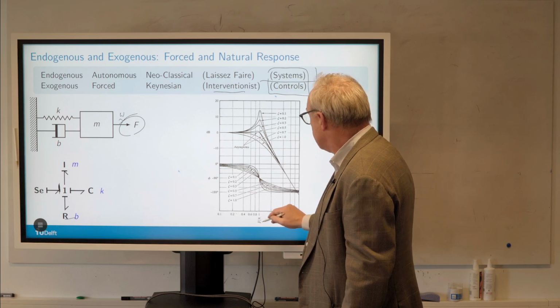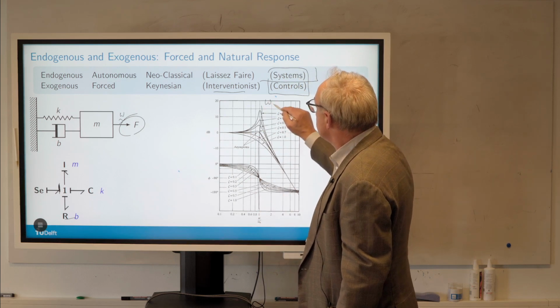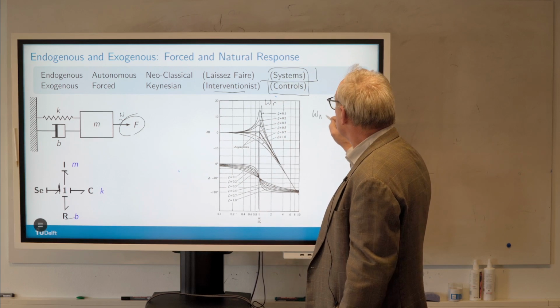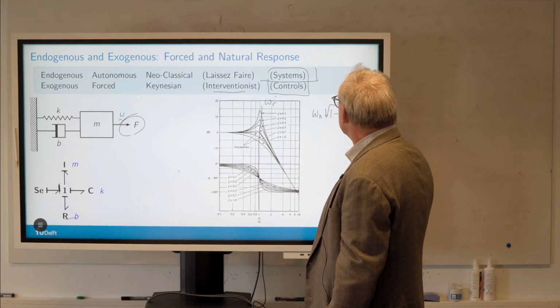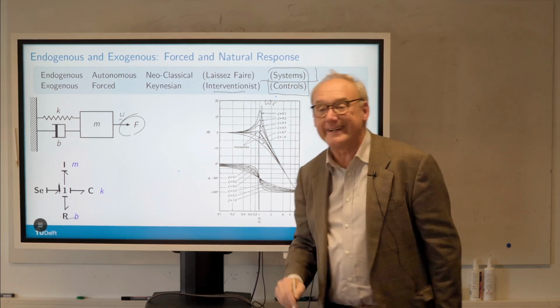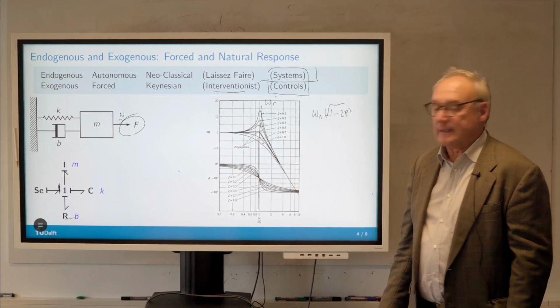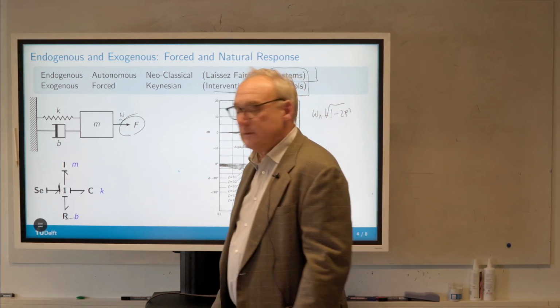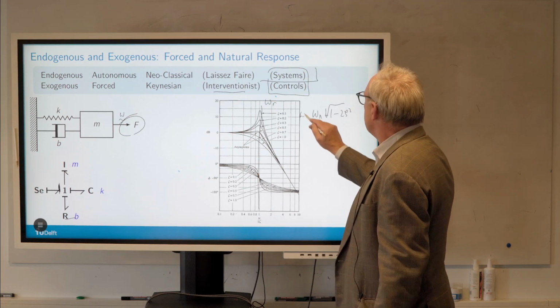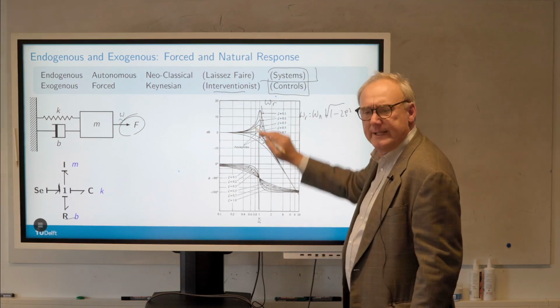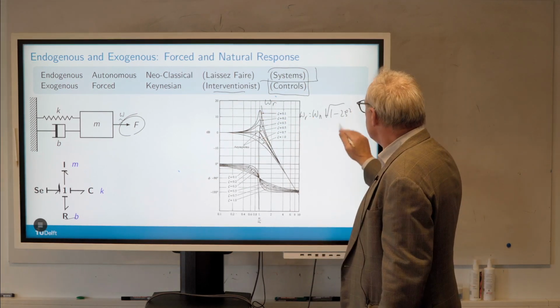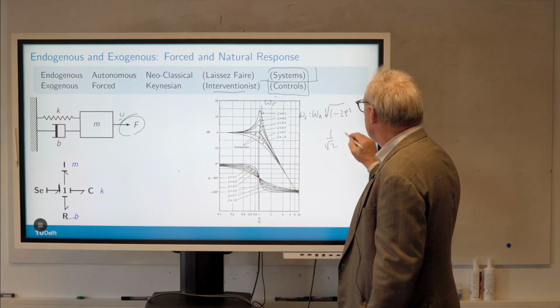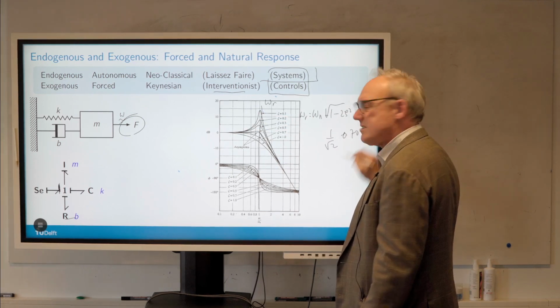You can look at, well, this will be the resonance frequency, right? What is that? Omega n times the square root of 1 minus 2 sigma squared, something like that, right? Without the 2. No, that's the resonance frequency. Oh, right, sorry. And I think that's the peak. I think there's a 2 because isn't the peak at 1 divided by the square root of 2, which is 0.7, something like that, right?